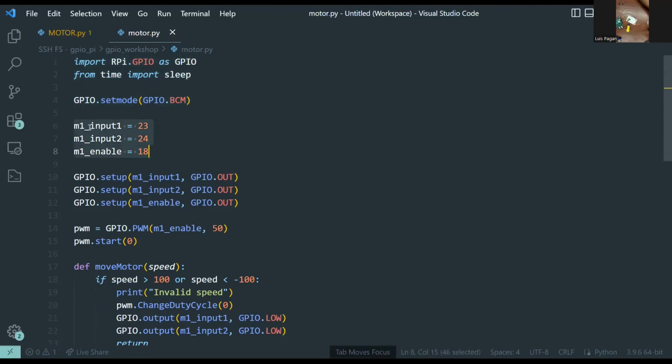So you want to make sure you have the input for this. This is assuming you have 1 motor, depending how many motors you have. So let's say if you're running another motor on the same side as this one, then you would need 5 different... oh no. No, you'd only need these 3 because they would be moving in the same direction at the same speed. So you'd only need 3. But let's say you use both sides of the chip, then you would need 6 because you need to do the enable for the other side and then both inputs for the other side.